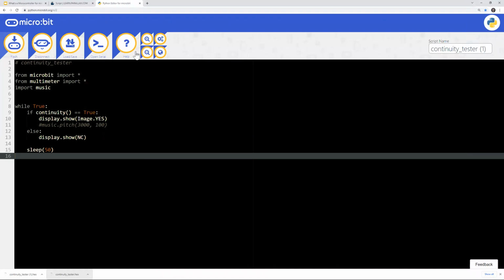All right, so web USB error. Okay, I'll disconnect. So if you try again, go ahead and OK out of your web USB error and click connect again. Does anything different happen the second time you do it? It immediately goes to web USB error again, almost instantaneously. Okay, so check, unplug and replug each end of your USB cable.